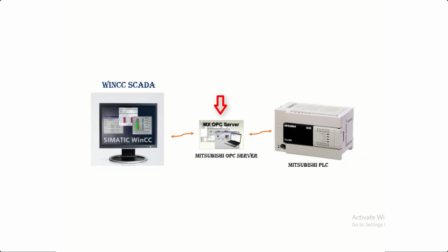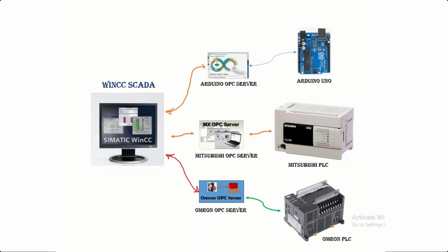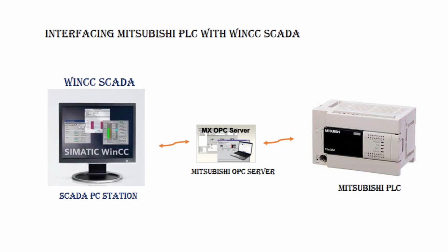In this project, MX OPC Configurator will be used as Mitsubishi OPC Server, which collects Mitsubishi PLC data in a standard interface so that WinCC SCADA software as well as SCADA software of any other vendors can access this data for SCADA application, provided those SCADA software support the OPC protocol. Similarly, you can also interface PLC of other vendors with the WinCC SCADA system using their respective OPC server. So let's proceed with how we can interface Mitsubishi PLC with the WinCC SCADA system using MX OPC Configurator.